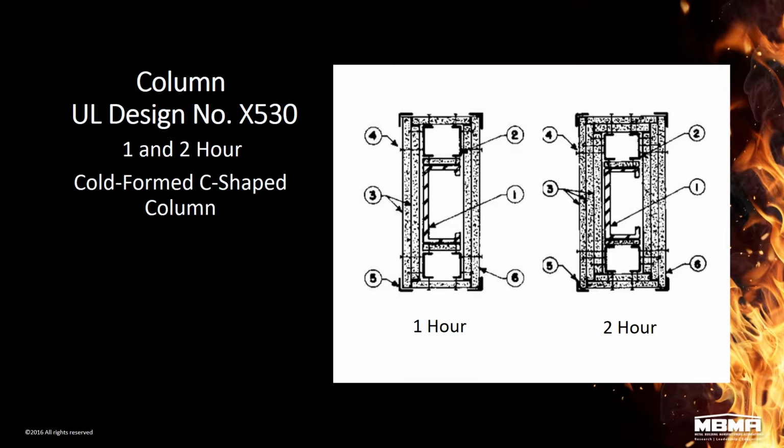It's also significant because it probably has one of the lower minimum W/D ratios, so the minimum sizes that are allowable for fire resistance rated construction are smaller. Again, it will give you the various requirements in terms of the gypsum board brands, types, and installation details for 1 and 2 hours.